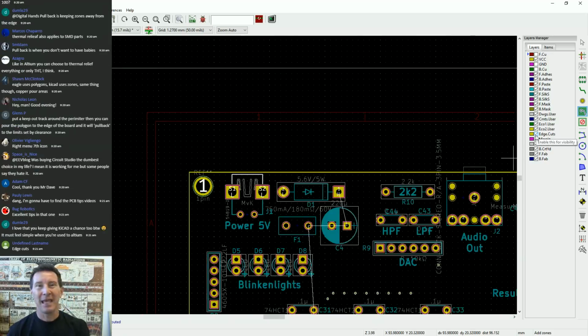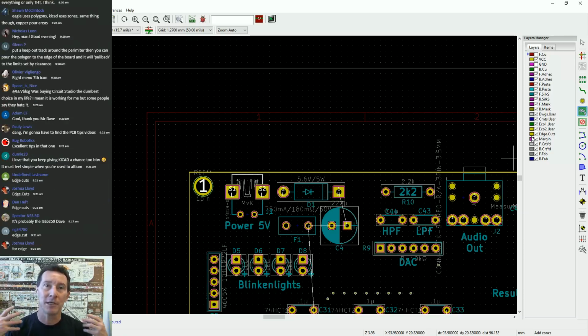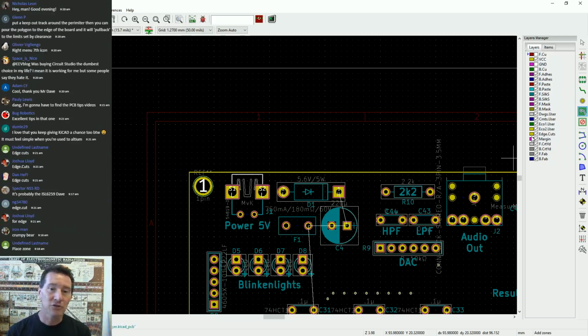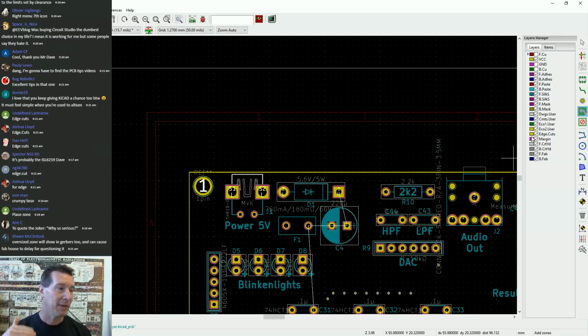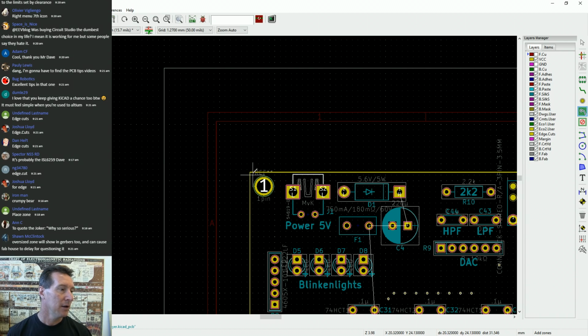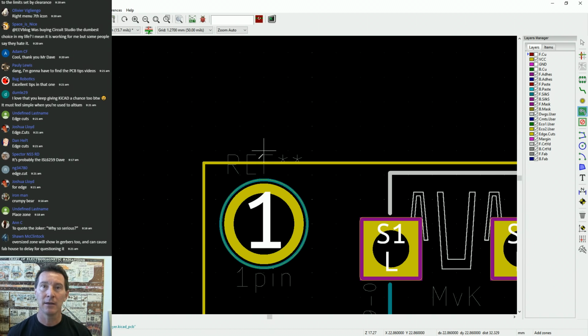It doesn't have to be on the edge cuts layer. It can be on the copper layer. It can be anywhere, as long as the PCB manufacturer knows. When they see lines like this, it doesn't matter what layer it is, they're going to know that you're implying that that's the edge of your board. Now, when they manufacture your PCB, they use either routing or big guillotines or saws to chop your board up, right?